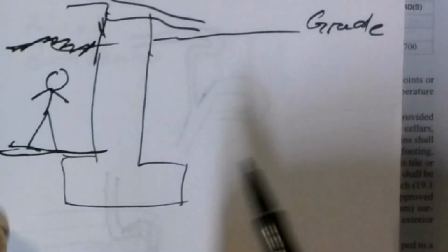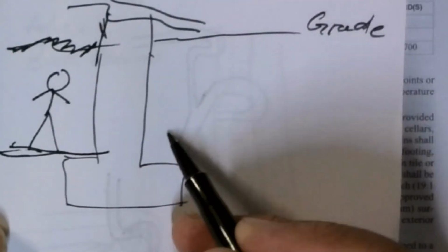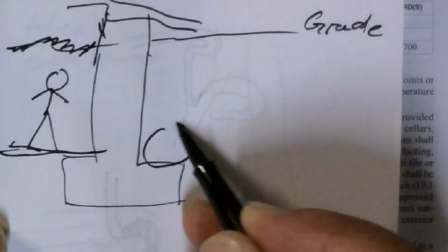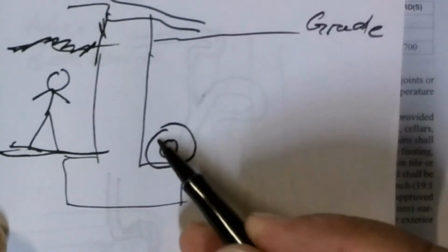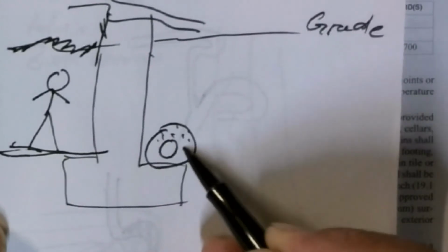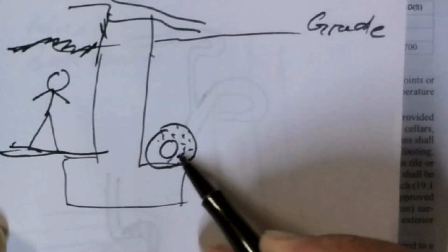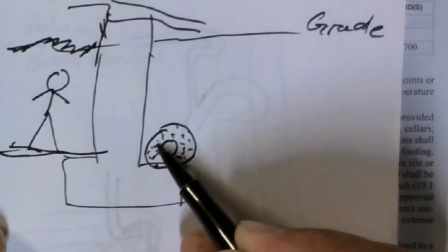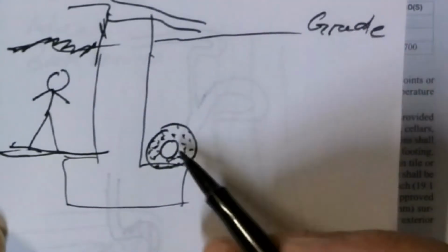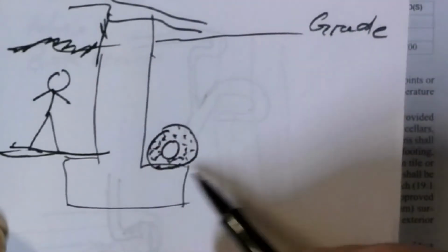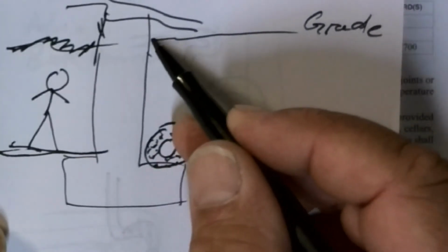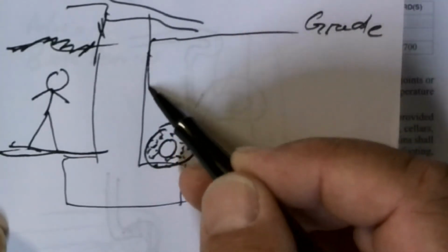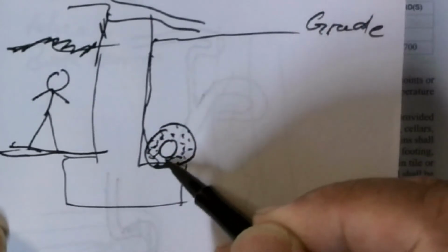Basement. This area here gets a 3-inch minimum pipe with rock around it. And this rock is all wrapped around filter fabric. So any groundwater that comes down, like here, and let's say wicks down, it's going to collect inside here.